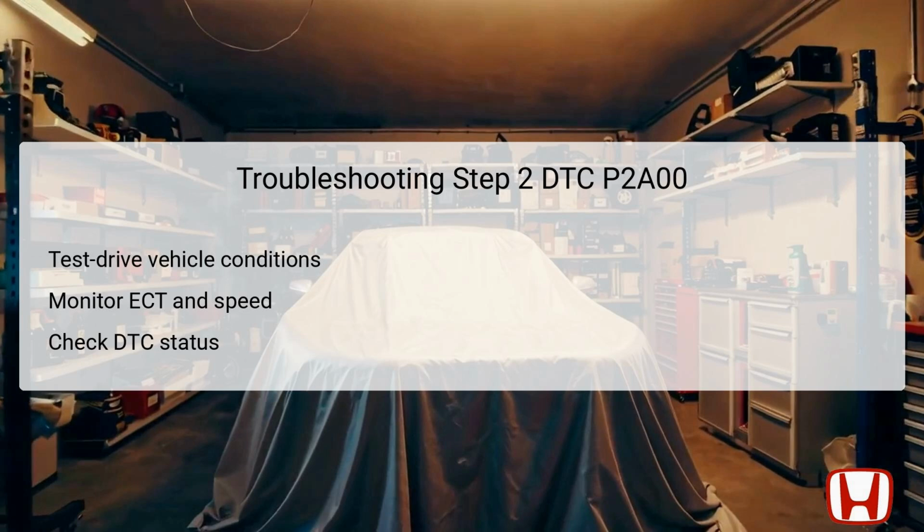After maintaining this steady speed, accelerate briefly between 55 to 75 miles per hour, 90 to 120 kilometers per hour, and then decelerate with the throttle fully closed for a minimum of 5 seconds. This step simulates real-world conditions, allowing the PCM to assess the sensor's performance accurately. After the test drive, the next step is to monitor the HDS, Honda Diagnostics System, for the OBD, onboard diagnostic status, and check if DTC P2A00 remains active.